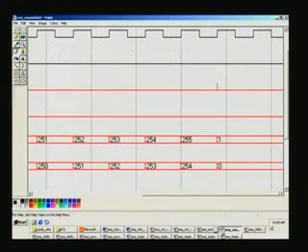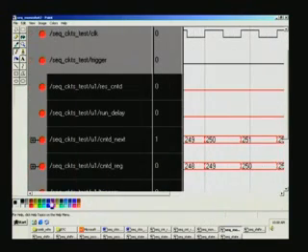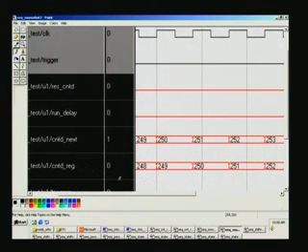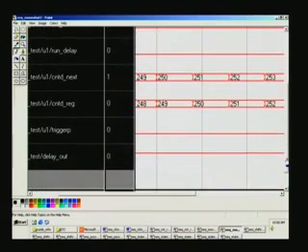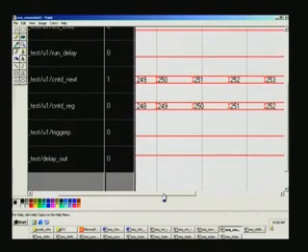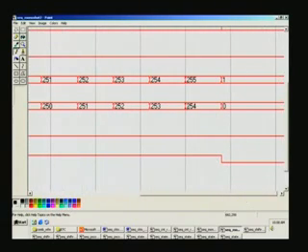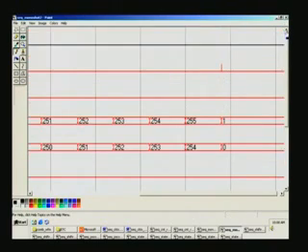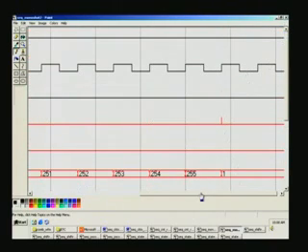So looking at the waveform once again, you see here 254, this is the counter edge, the last one, right here, and this is delay out. Finally, it is still 1 here, and now when it is 254, at this point of time, instead of 0, actually 255 has come over there, and because of the combinational action here, that reset control D, that is here, right?